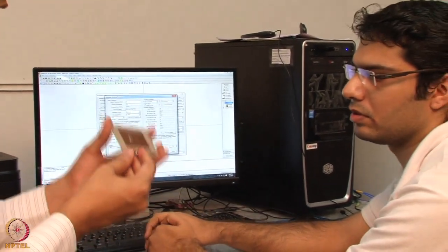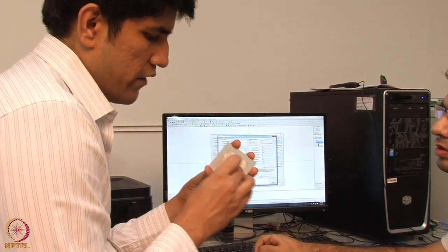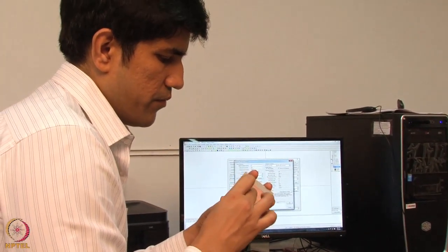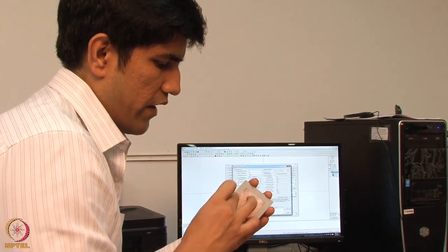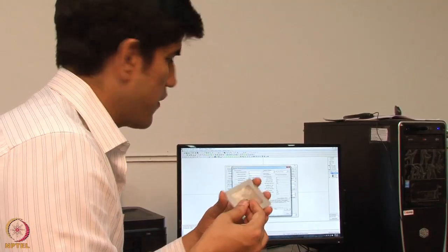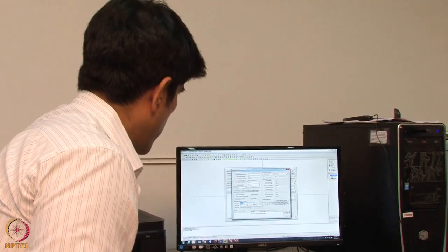What is important is that near the feeding area the meshing is fine enough to capture the resolution, whereas in the outer areas you can have a very coarse mesh. That is what this parameter controls. Okay, let's go forward.